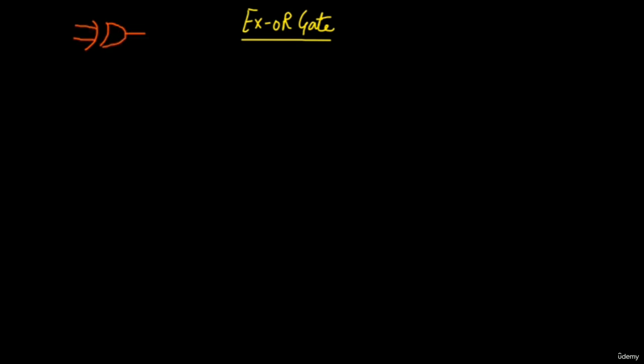And obviously this is a traditional symbol. Now it's time for the IEC symbol. So the IEC symbol seems something like this, the box, and these two lines is equals to 1. We write in this case equals to 1. Now this is the output and these are the inputs. So these are the inputs and this is our one output. Same for this output and inputs.